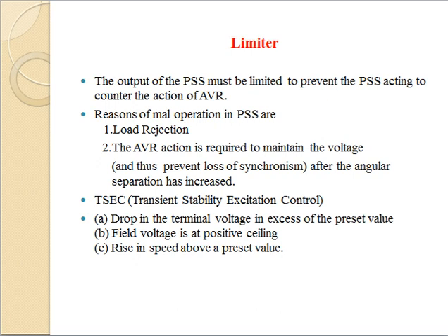Now, the reasons for mal-operation of the PSS: the first reason is that sometimes load rejection occurs. When load rejection occurs, the AVR must come into operation and make its terminal voltage constant.